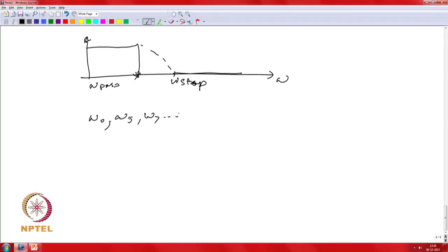Your harmonic frequencies in your pass band, especially if you are trying to build an active filter which is trying to inject and control the harmonics in an accurate manner. You might also say, for example, try to reject the harmonics that the grid is putting on your power converter by actively ensuring that your bandwidth includes your harmonic frequencies. So your pass band needn't just be your fundamental frequency, it can actually extend further out depending on your bandwidth targets of your power converter.